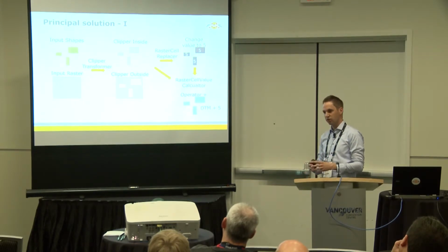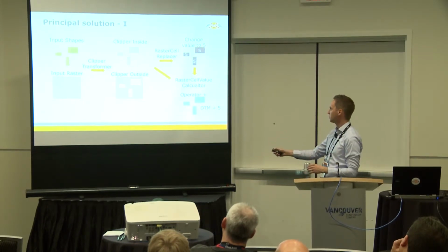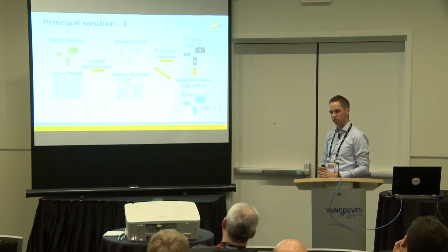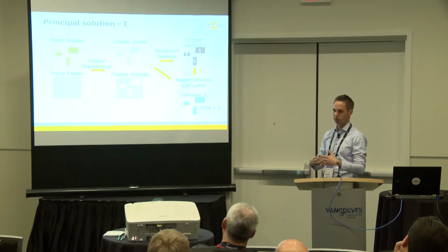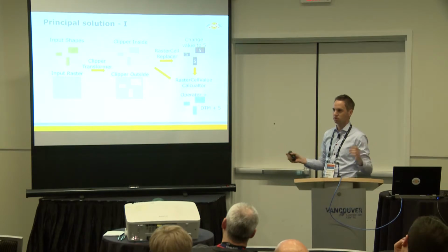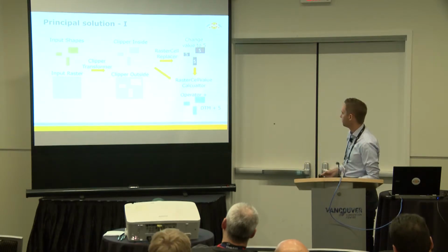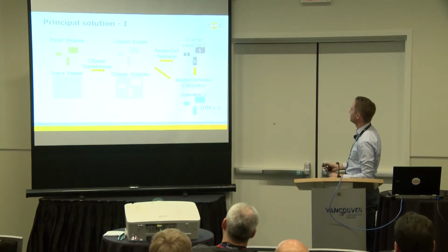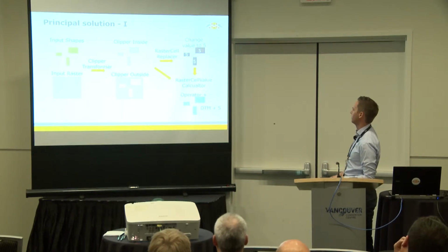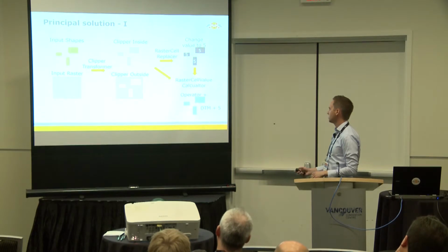The first thing I did was to convert that raster results to points, and then just changing the set value and then interpolating it back to a DTM. That works fine, it's a good method, but if you're using a very large raster, it takes a lot of time to do it. So I was very happy when I found the raster cell replacer and the raster cell value calculator. So I actually found a method.